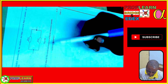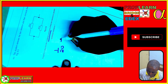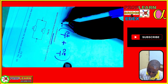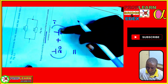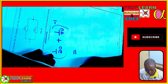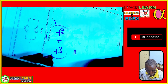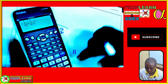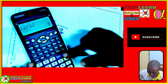Now, suggest the combined resistance. For this, we're going to say 1 over 20 plus 1 over 40 when they are in parallel, raised to power -1. So anytime you add them like this, you have to find the reciprocal to get the total resistance. So we are going to say 1 over 20 plus 1 over 40 raised to power -1. And if you work it out, that is going to translate to 40 over 3, which is approximately